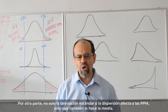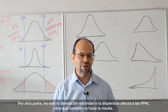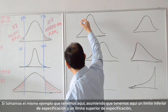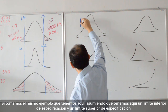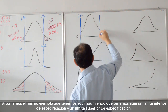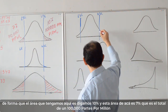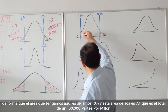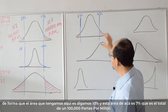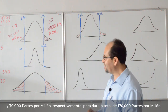But on the other hand, it is not only the standard deviation or the spread that affects the PPMs, but also the mean. If we take the same example that we have here, assuming a lower specification limit and an upper specification limit here, the area here is, let's say again, 10% and the area here is 7%, which is 100,000 parts per million plus 70,000 parts per million, a total of 170,000 parts per million.